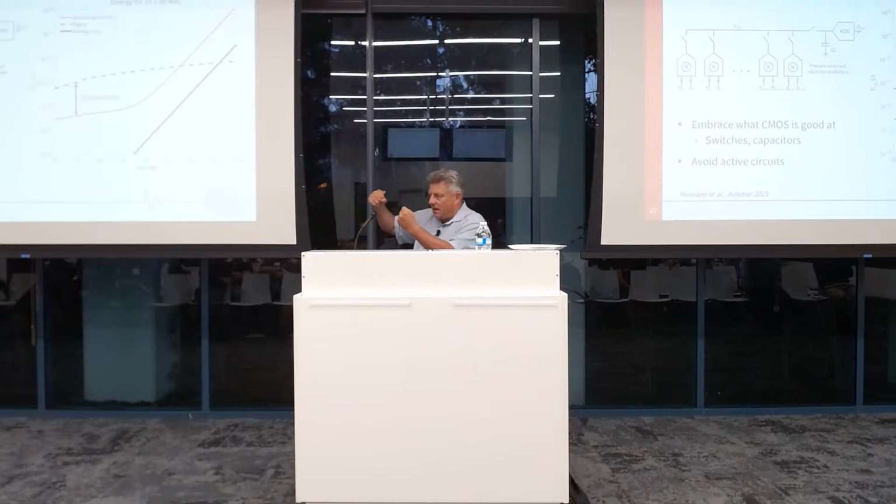With that comes some complexity and excess noise and things like that. That's why the complexity pushes you away from that limit. And it's parallel to that for very high resolution. These decibels are signal to noise ratio. If you divide this by 6, roughly speaking, you have the number of bits. So this is 10 bits, and here at about 8 bits, 6 bits, and so on. But this is parallel for high resolutions.